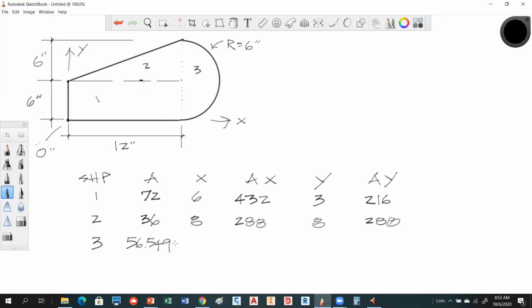All right, now watch this. This is going to be probably a little bit strange, but we know that the origin to the face of this semicircle is 12 inches, right? 12 from the origin to that, but we're actually going to be out here. So our YY centroidal axis is out here. If you look at that chart, you'll notice that they have 0.4244R. So this distance from that point to that axis is going to be 0.4244 times 6.